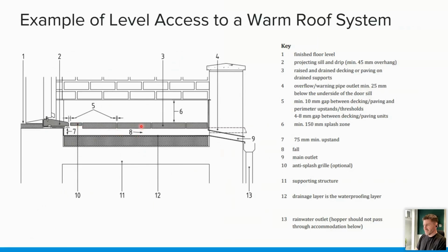Important again is the fall, is that the fall is going away from the threshold. We don't want falls going towards any kind of upstands really. It's quite important that falls go away from the upstands if we can.